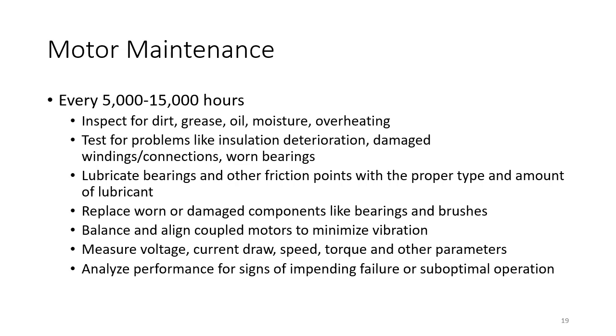You might also want to look at the voltage, current draw, for speed, for torque and other parameters, just to make sure that the motor is still operating within its required parameters. And then they could potentially, if they're changing, indicate other signs of problems with the motor. And overall, what you're looking at is analysing performance just to see, is the motor about to fail, or is there suboptimal operation? And if there are problems with the motor, you could either replace the motor, or potentially you could get the motor refitted or reconditioned.